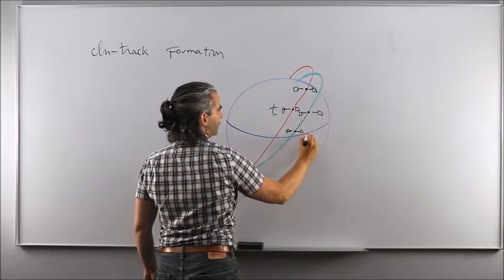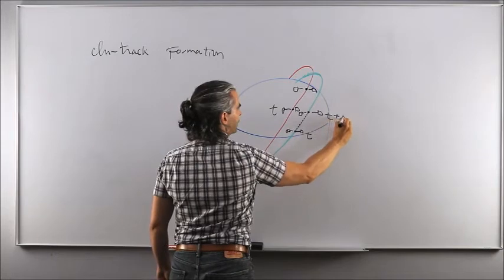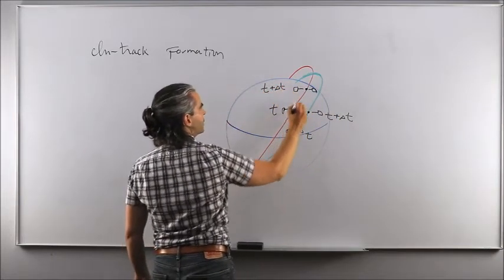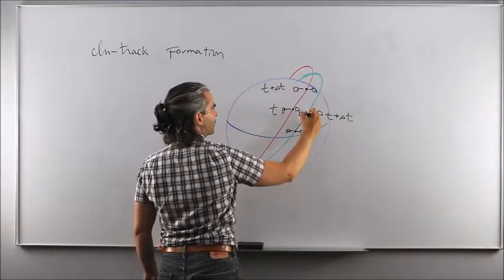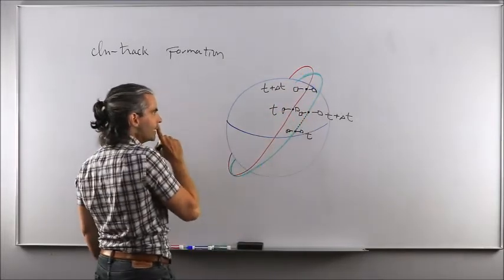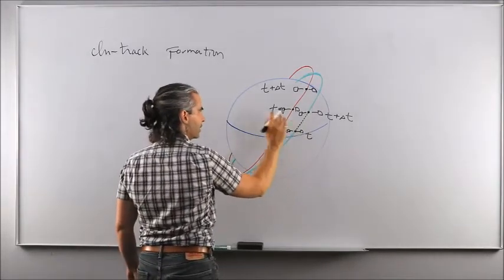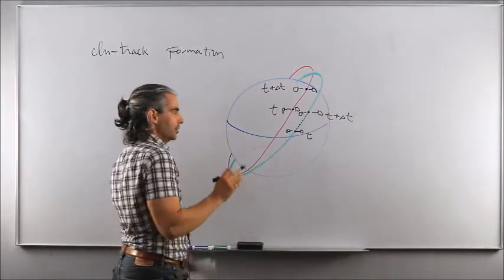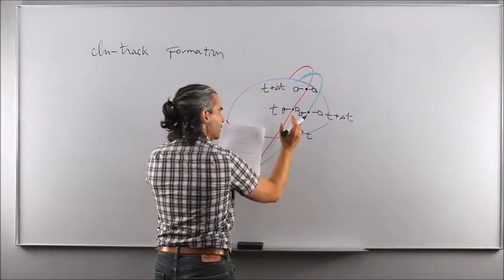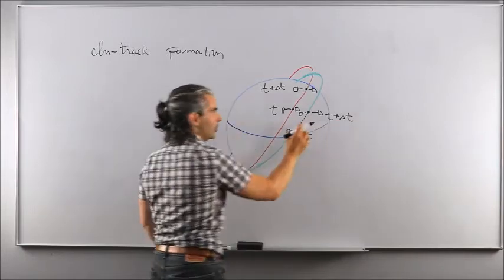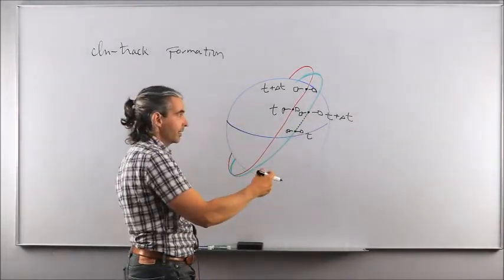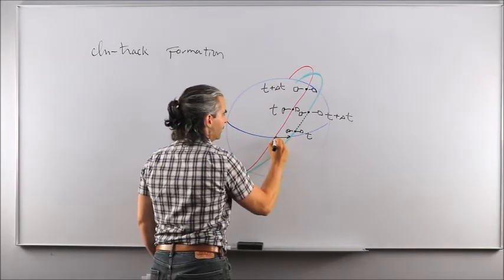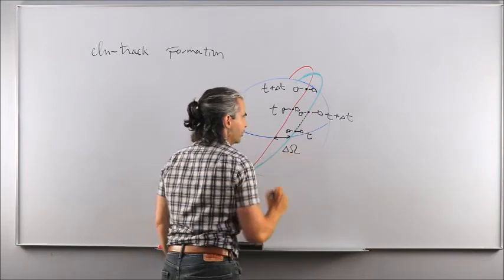So that was at t, and now this is t plus some delta t, and that one at this future time is now further north. This one is right over Ottawa, and the reason why it is like that is because Ottawa moved eastward in that amount of time. So you need to separate the orbit according to the delta time at which you want both spacecraft to fly over the same spot. And that separation is being translated by a change in the right ascension of ascending node.